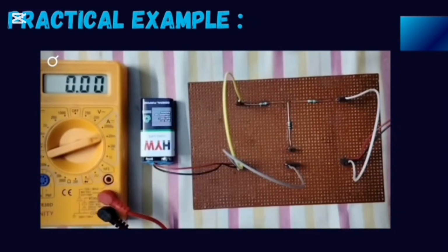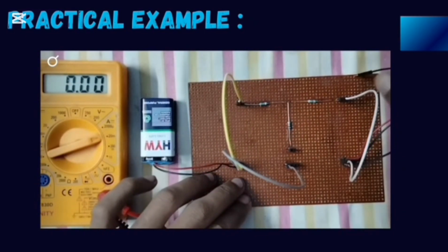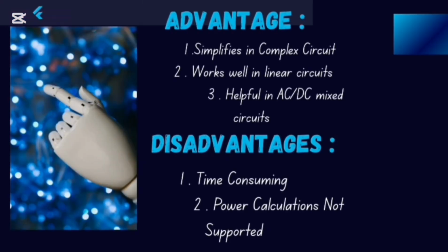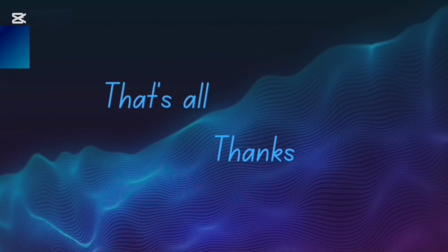In this video we saw how to apply superposition theorem and saw the voltage source. Then the last topic is advantages and disadvantages of superposition theorem. Firstly, advantages of superposition theorem: it simplifies complex circuits, works well in linear circuits, and is helpful in AC or DC mixed circuits. And disadvantages of this theorem: firstly, it is time consuming, and lastly, power calculation is not supported.